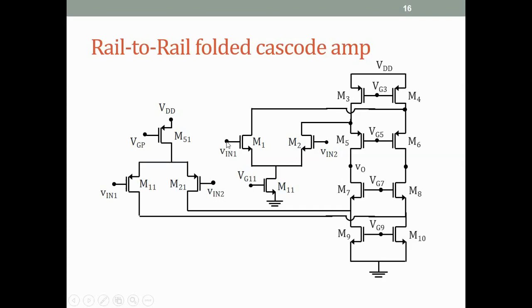As Vc is increased above 0.6, let us do this for VDD equal to 3 volts, just to generalize. So VDD is 3 volts, the NMOS differential pair turns on at 0.6 volts common mode input, and the PMOS differential pair stays on up to 2.4 volts.